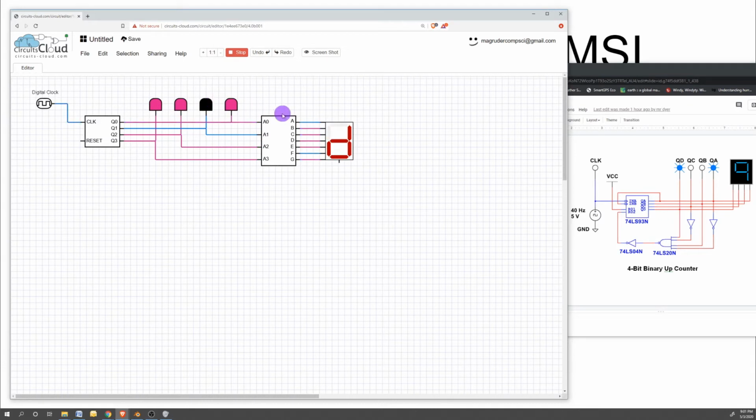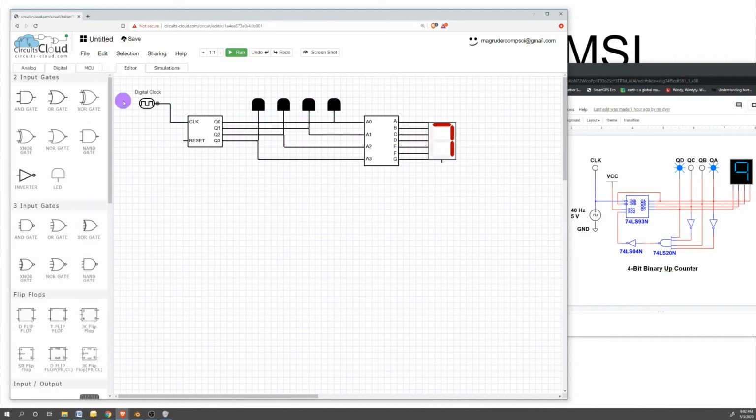This is important for our actual control logic because we want to remember what we're really doing here: we're using this counter to count for us automatically, but we want to reset at a very specific value to simulate that we're only counting from 0 to 9. Again, that modulus 10 behavior. And so we've got the basic design here. How you build this control structure is up to you, but please do it in a readable way that makes sense.